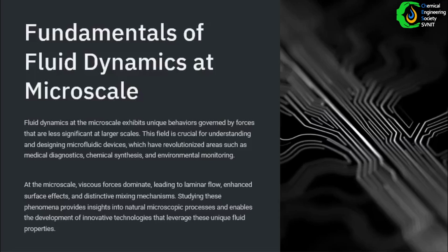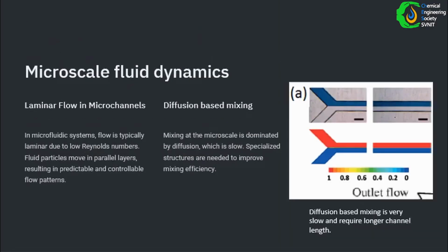Let us now understand fluid dynamics at microscale, and how it is different from macroscale. Fluid dynamics in microchannels is governed by principles that differ from those at macroscale due to the small dimensions and dominance of forces like viscosity, surface tension, and diffusion. In contrast, macroscale systems are often dominated by inertial forces, convection, and turbulence.